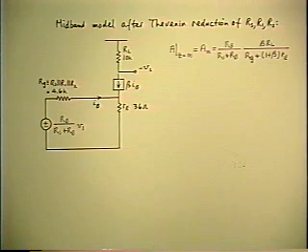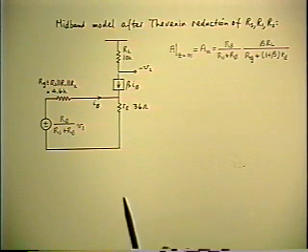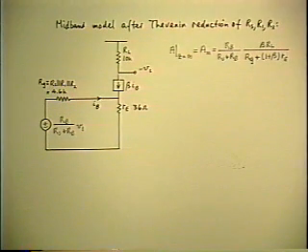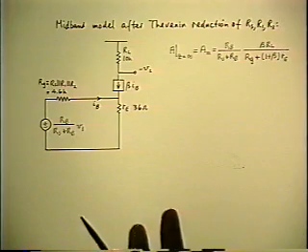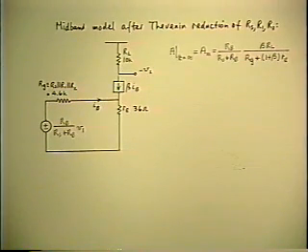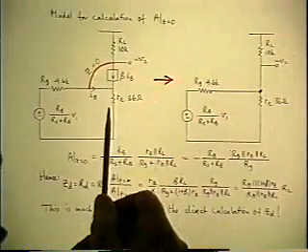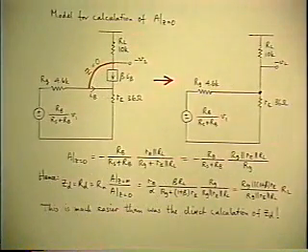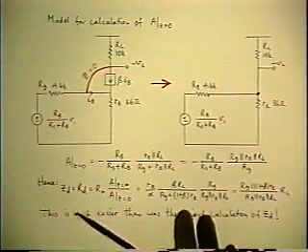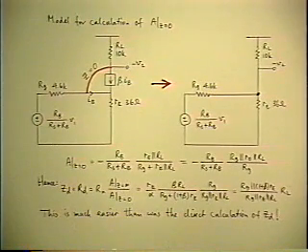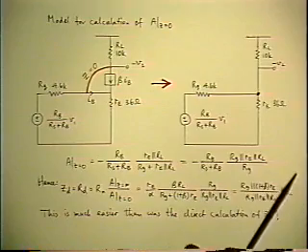So now, instead of calculating the Zd directly, let's calculate the other reference gain, which means you go back to your reference model and now you simply put a short circuit in place of the extra element. Already you can tell it's going to be easy.